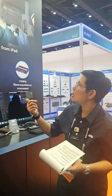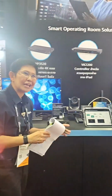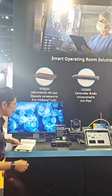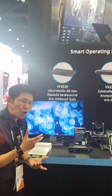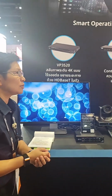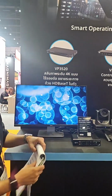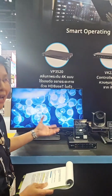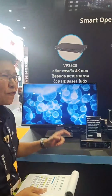Okay. Our smart operating room solution, in fact, combines our ATEN Pro AV system for the operating room. The first one is the VP2420. This one is a true 4K seamless switch. It supports 4-channel HDMI input and 2-channel HDMI output, so you can connect the surgical camera to the HDMI input channel to make sure you get the signal at 4K 60.